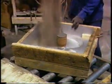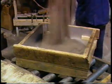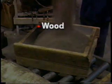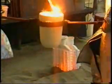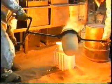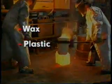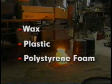Many casting processes utilize patterns. These are used to form the cavity of the mold into the shape to be cast. Reusable patterns are made of wood, plastic, or metal. Expendable patterns, so called because they're consumed in the mold-making process or by the poured metal during casting, are made of wax, plastic, or polystyrene foam, depending on the process.